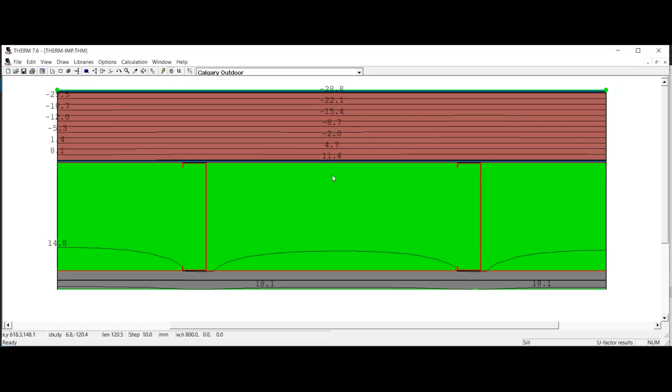Aha. Okay. Oh yeah, by the way, I made this insulated metal panel 100 millimeters because I was told, I didn't dig into it too much, but I was told that that's the maximum thickness you can get if you use the mineral wool core. So here we go. So we're minus 30 on the outside. By the time you factor in the exterior air film and work your way through the insulation, obviously the temperature starts getting warmer.